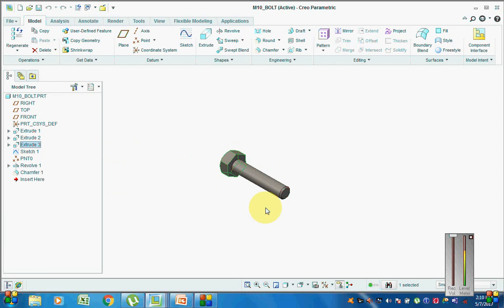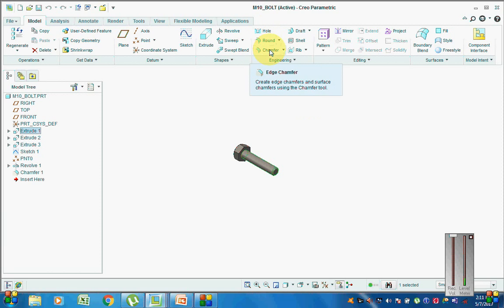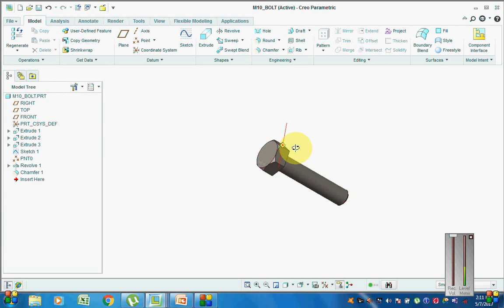It tells you. And this is one advantage of 3D CAD software over 2D CAD software. 2D CAD software does not tell you how a model is built. If you want to change the model later on, you can't do it easily, and it is a lot of time consuming work. So these are all called features. Extrude is a feature, revolve is a feature, sweep is a feature. We will deal with this in our later tutorials: how extrude is used, how revolve is used, how sweep is used, how hole, rounds and chamfers are used to make these features. So this is the feature based concept.